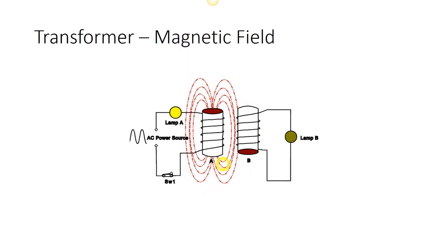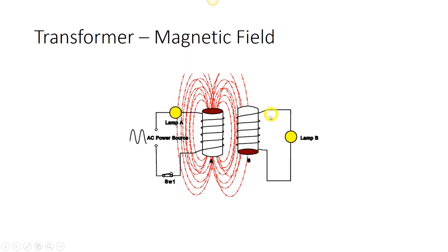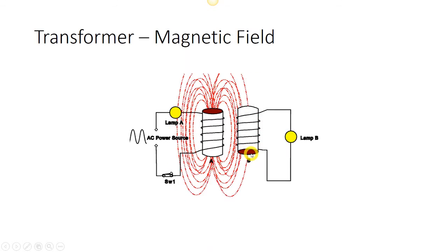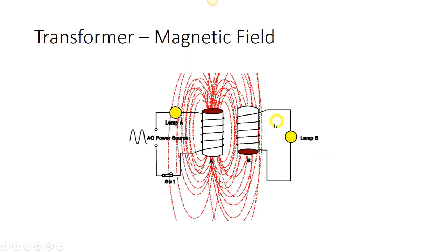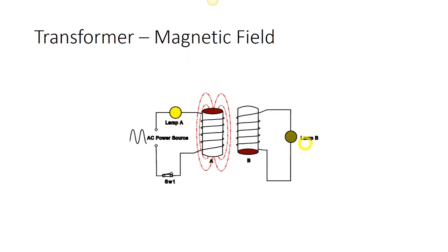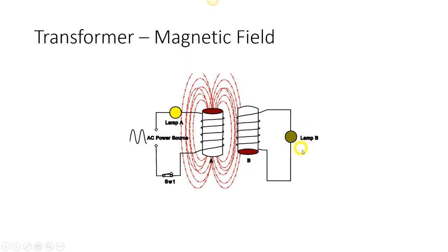They would happen extremely fast, but this animation here is showing you, if you had a lamp on that side, that when you are cutting these lines of coils in this secondary transformer, you're actually producing some current, and then if you have current, you have a voltage drop across the lamp, and the lamp is energized. It's energized while the magnetic field is either expanding or collapsing, but as we know with AC, the AC sine wave, sometimes it's passing through zero. And so there will actually be a time that the lamp is off.